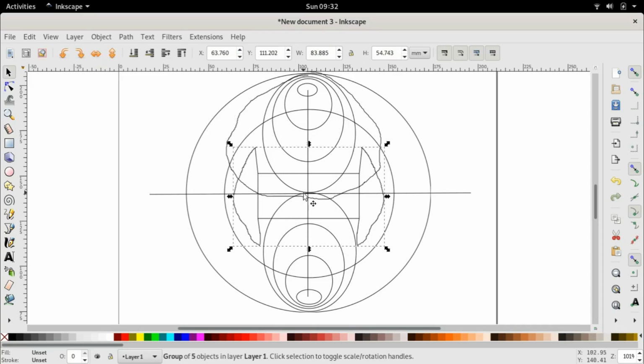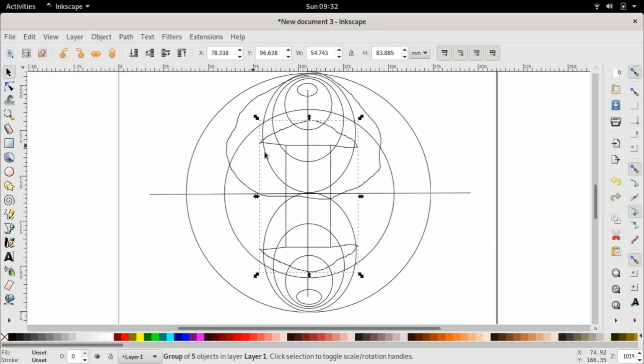Why? Because the flux can flow through the midsection and through this entire salient pole. Whereas in this position, the flux can only flow through a small part of the salient pole itself. So in this case, the reluctance is maximum and the flux is minimum.